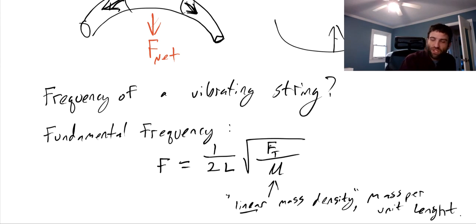Okay. And so dimensionally, you can check that the dimensions of everything work out, right? So we have force, which is, for instance, in units like kilogram meter per second squared, divided by kilograms per meter. So all told, that's going to be, after taking the square root, meters per second divided by meters. So 1 over seconds, or hertz.